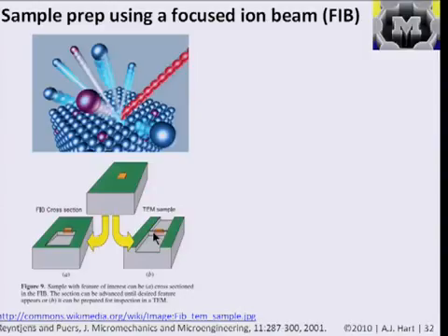I don't have a picture of a focused ion beam here, but you can imagine it essentially as an SEM, a vacuum chamber that can take a picture while you have another beam coming in that lets you machine things away. So you can watch the SEM image and drive the FIB, and you basically see material disappearing before your eyes as you cut it away using the ion beam. It's not a perfectly clean process.